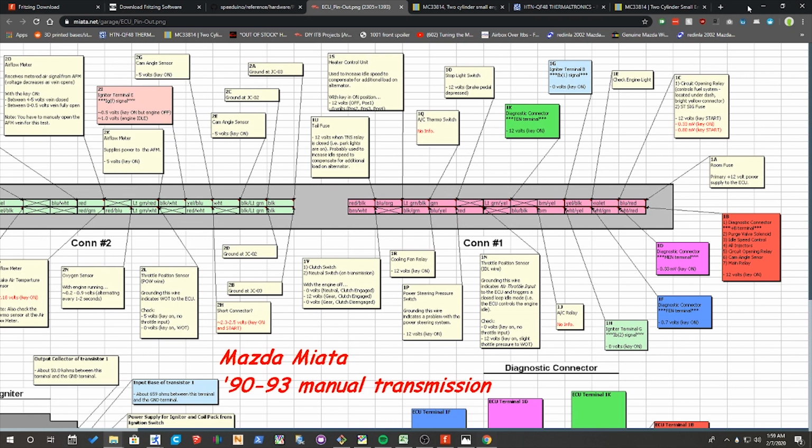Thus, in order to check and see if our ECU is receiving power, we can grab a voltmeter and check pins 1A and 1B to see if they're receiving 12 volt power and switched 12 volt power respectively. Along with this, we've got blue red and white red indicating the colors of the wires. That way we can 110% make sure that we're checking the voltages of the correct wires. I'll leave a link in the description to this pinout in case anybody else needs it, but Google will be your best friend in order to look up any sort of pinout that you could ever need, essentially.